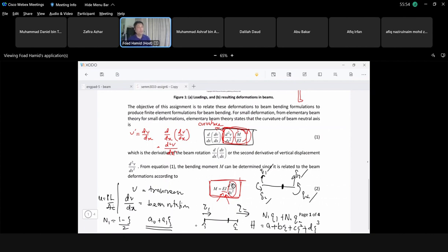So now it's a polynomial of the 3rd order, because we know 4 values. The highest order that we can construct is a 3rd order polynomial. So the question is, what is A, what is B, what is C, and what is D? And note that H is a function of the location in the natural coordinate system, which is Z.